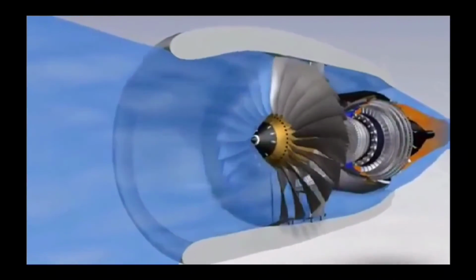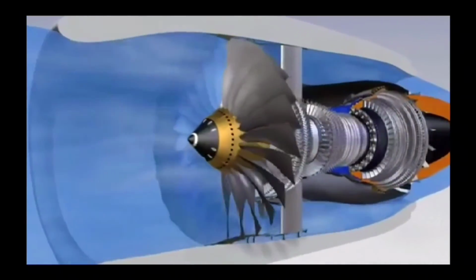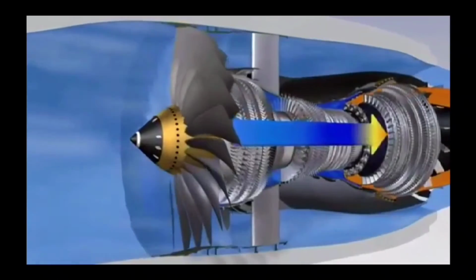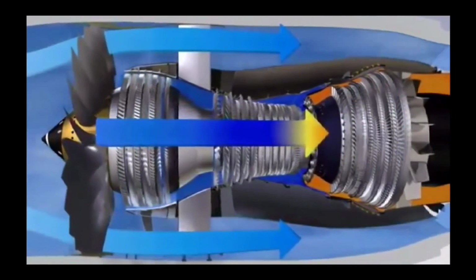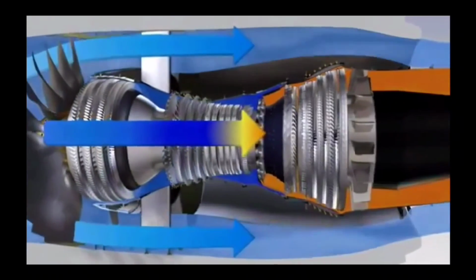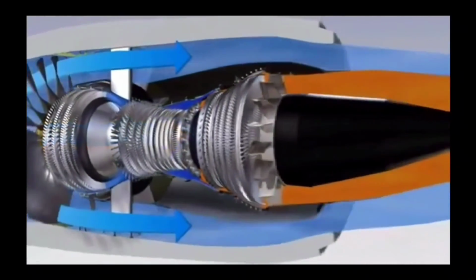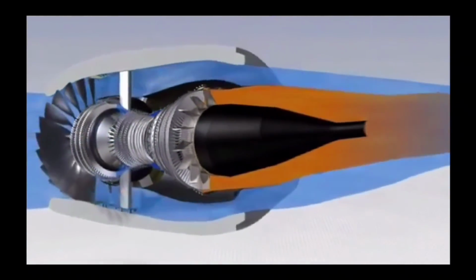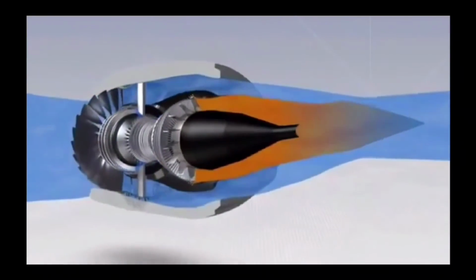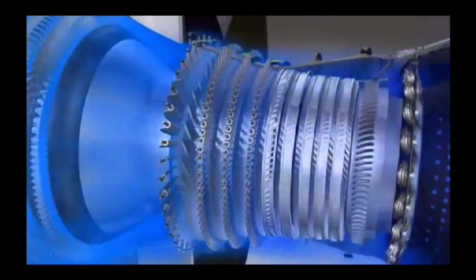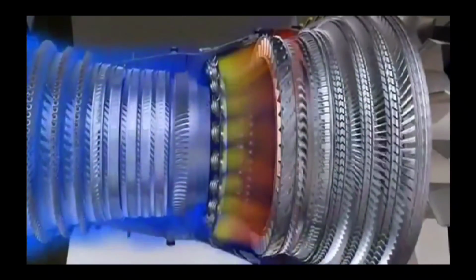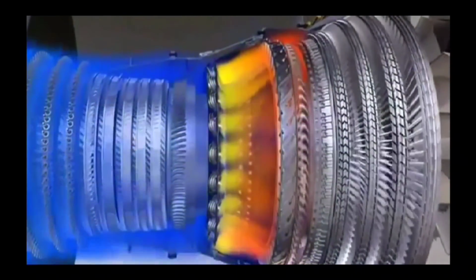The CFM56-7B is a high bypass ratio engine. The primary flow passes through the combustor, while the secondary flow passes only through the fan. 80% of the engine airflow, accelerated by the fan, is directed into the bypass duct and provides 80% of the engine's thrust. The primary flow passes in succession through the compressors, the combustor, and the turbines, before being ejected rearwards